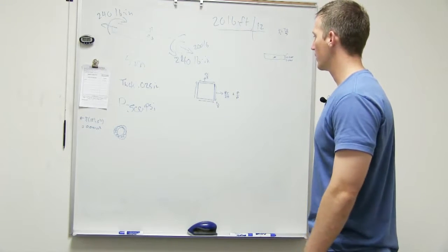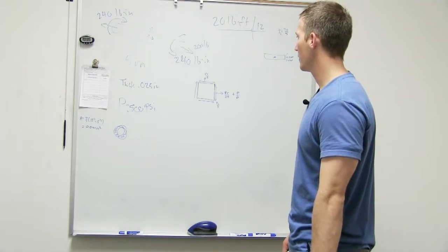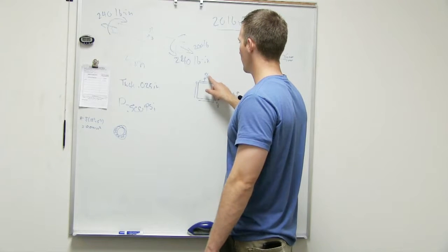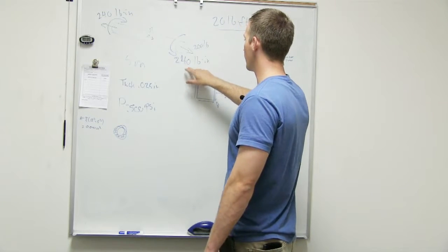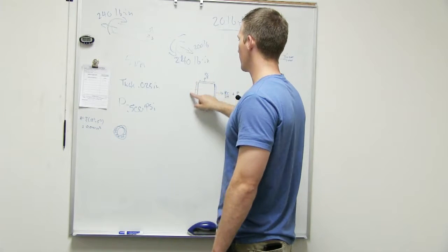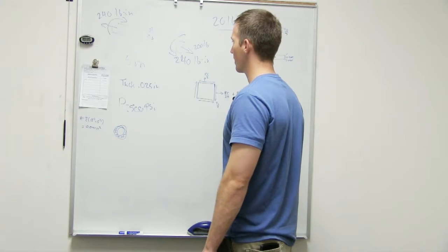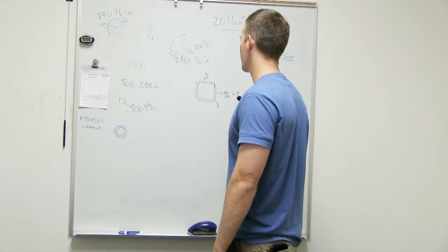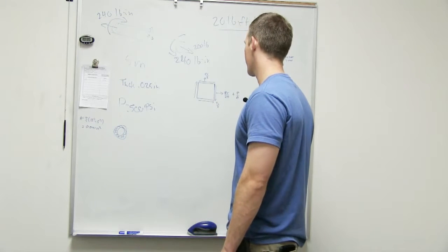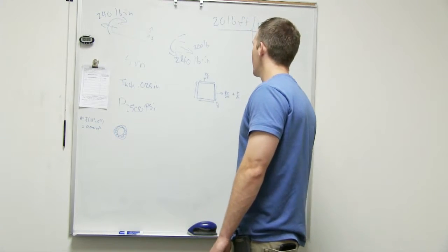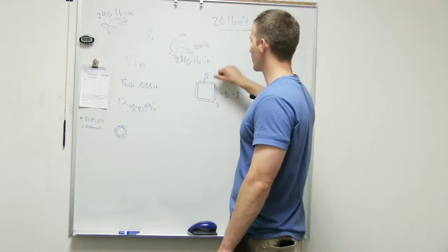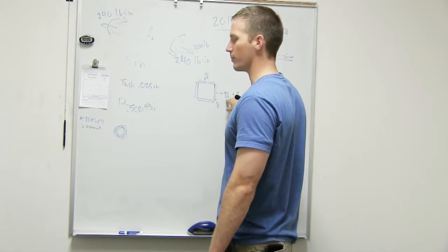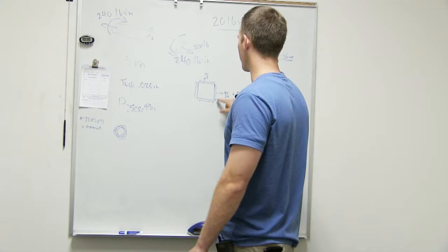And then going up, does the 240 also act on that? The 240 only creates shear stress. Okay, I was just wondering that. Then the 500 has to do with the PR over T then. Yeah, so that's going to put both of these. That's both of those already. That's the pressure times the radius over the thickness. And so the 500 is causing those. The 200 is adding to the stress already from the pressure vessel. And then the 240 is causing some shear stress.